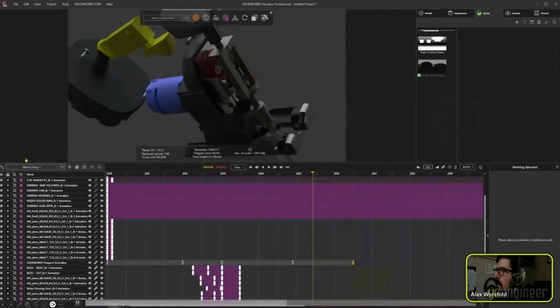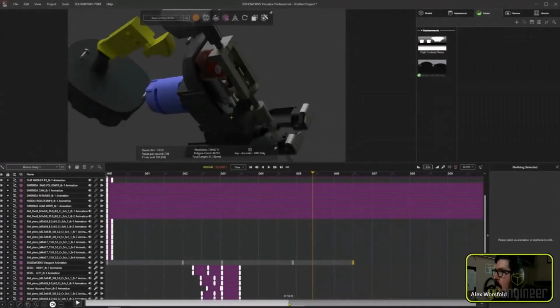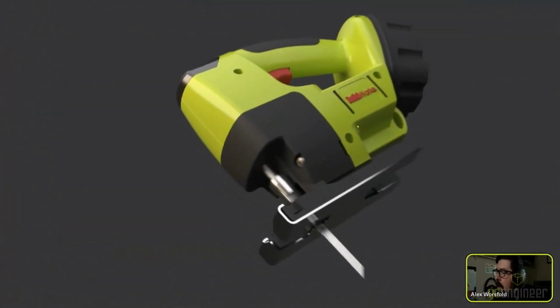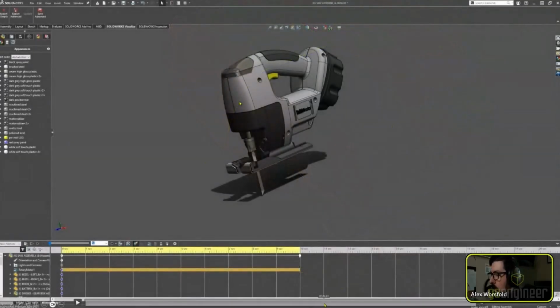Adding lights. So for example, I want to add a new light to my scene here. All I need to do is right click over here in the Environments tab, add a new light, and then pick the target of where that light needs to be placed. So all I did is pick within that section there, and I skipped ahead too far.